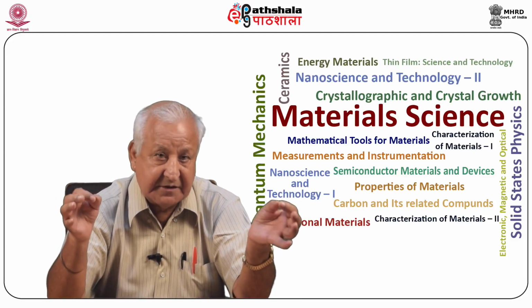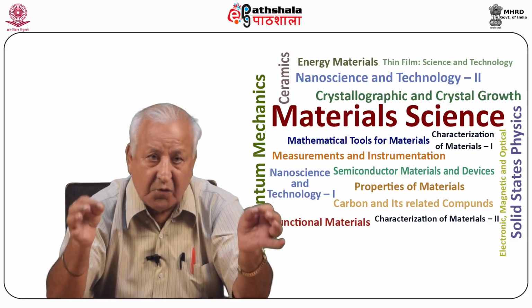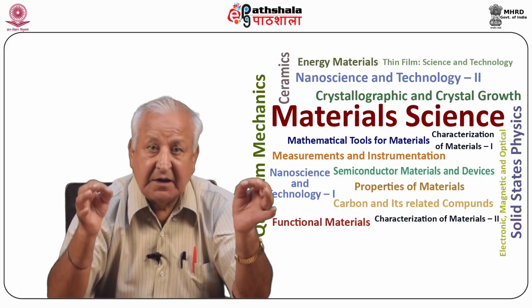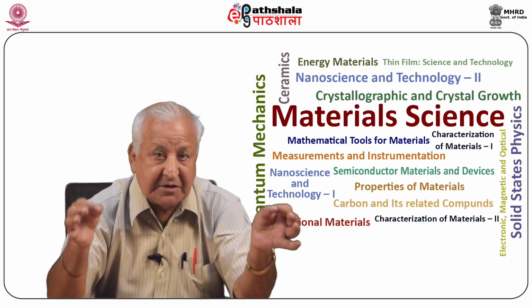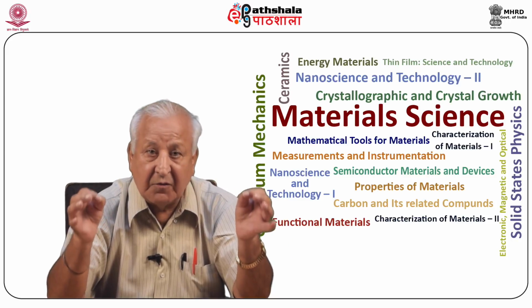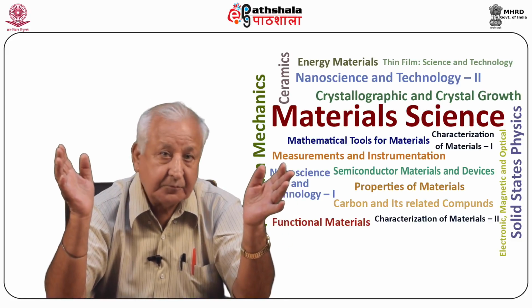After 6 hours, mixing is stopped and the temperature is lowered at a steady rate of 4 degrees centigrade per hour for 8 days. At this stage, the furnace is shut off and the crucible is taken out. As the temperature passes 1240 degrees centigrade on the way down, the solubility of ruby is exceeded and the crystals grow as the temperature is further reduced.